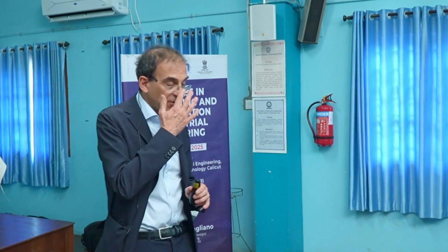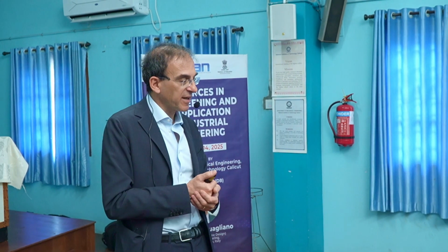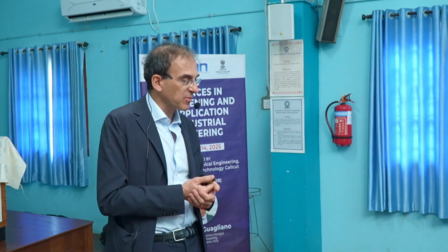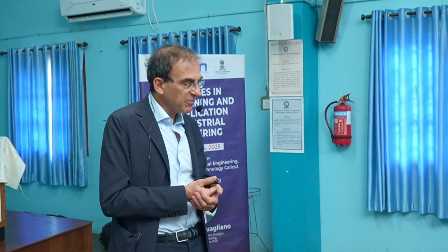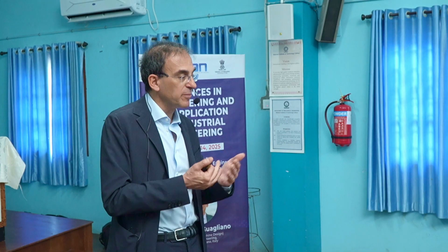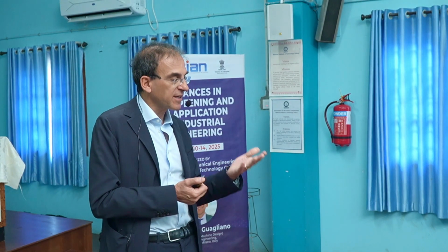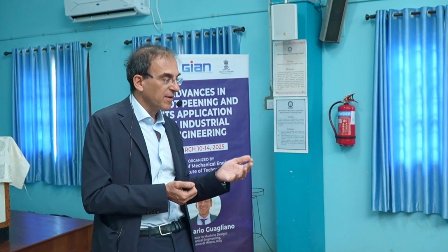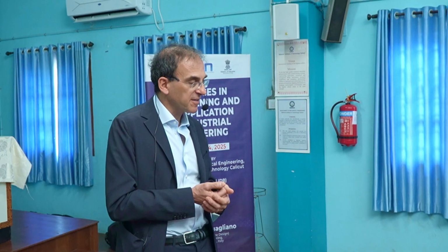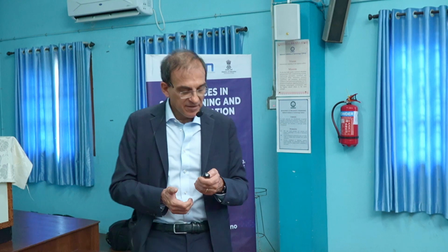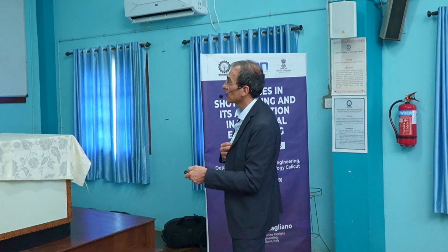We don't care now in this slide about the parameters. We assume that it is well done. With conventional shot peening, we are able to improve what we can get by using preset only. That is to say, we increase the fatigue limit from 140, let's say, to 150. This can be associated to a different residual stress, that is this one.